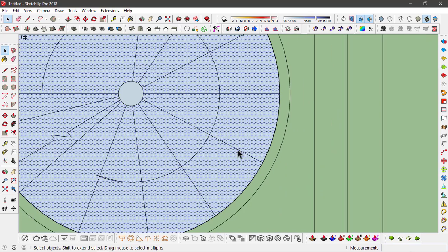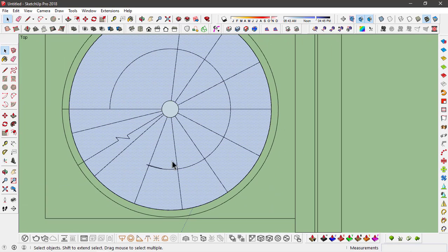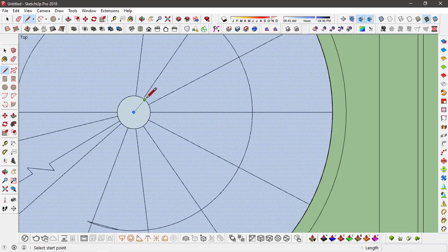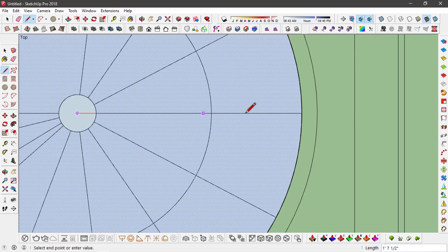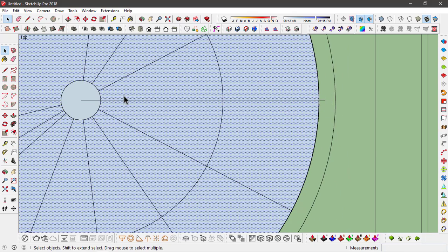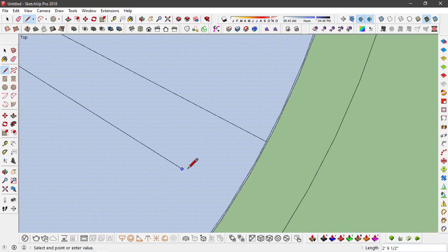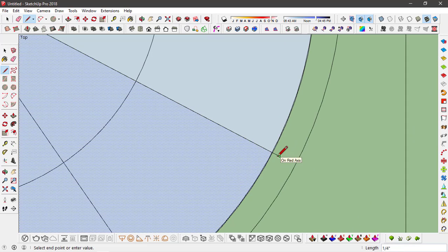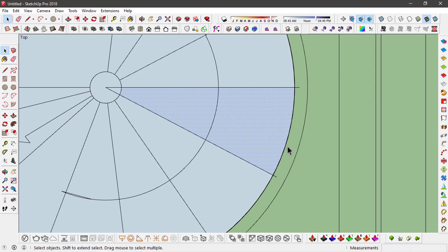We need the circle face to basically make the steps of the stair, and let's go ahead and make a step. And to do that I'll create a line starting from the center point of this smaller circle and follow this line up till here and make another line aligning it to the edge on the CAD drawing. So now we have this face that will be our step, or one single step for this staircase.